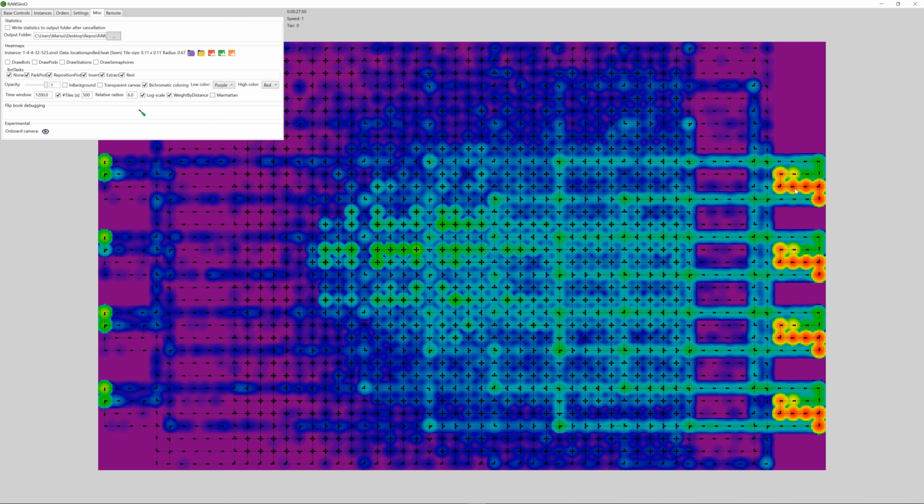And this happens if the configuration for the task allocation has a limit on how many robots it can send out to a pick station. And so you get an understanding via the heat map of why the behavior happens, or where congestion may happen, and so on. That is also what we can see over here. So these lines are actually very relevant. So we may want to choose a different setup here for the highway part of the grid, and so on. But I hope this helps in understanding what's going on.